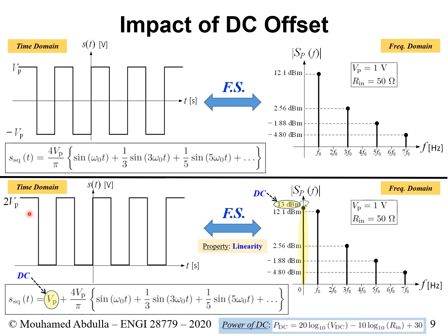You look at this one here. You say, okay, fine, I have a square wave signal. It goes between 0 and 2 VP. That looks fine, but what is the average value? If I were to average this waveform that goes up and down, the average will be in the middle. And the middle between 0 and 2 VP is basically VP. That's the average. So averaging your signal in the time domain by simply looking at it is another trick for getting the DC component very quickly. So that's a fourth way.